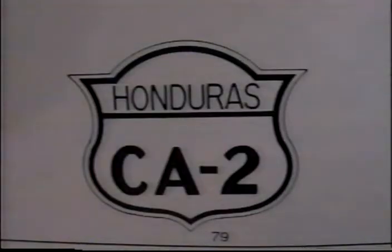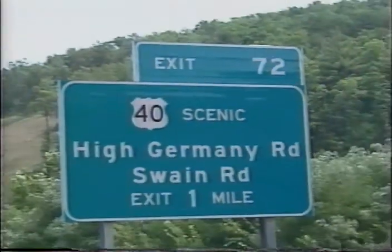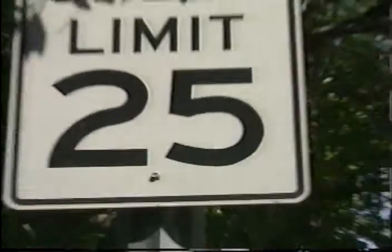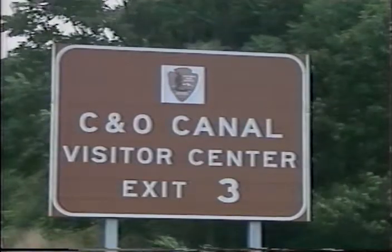Common colors and associated meanings are red, stop, yield, movement prohibition; green, directional guidance; yellow, general warning; blue, motorists' services; black on white, regulation; orange, construction zone; and brown, recreational or cultural facility. Common shapes for all systems are diamond, rectangle, pentagon, pennant, octagon, equilateral triangle, circular, and shield.